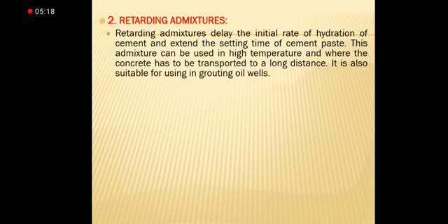Next, retarder admixture. Retarder means it will reduce the rate of hydration and extend the setting time. We don't want our concrete to set very quickly. We want it to take some time, so we have to use retarding admixture. Gypsum is a very good admixture which is nowadays used in concrete.